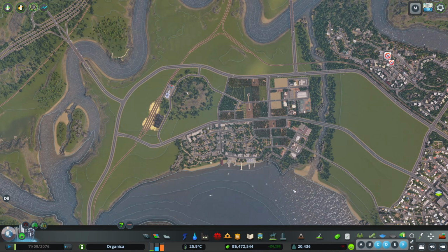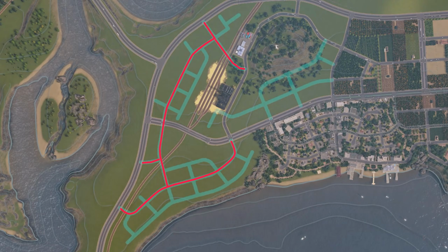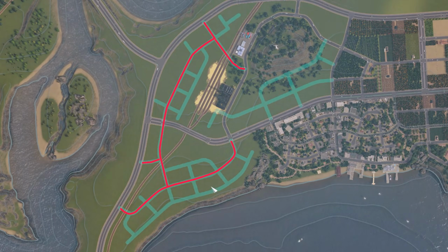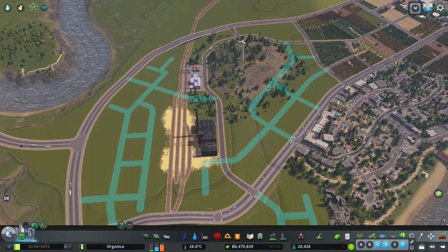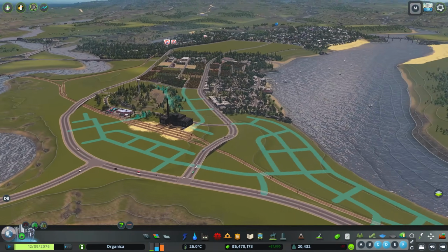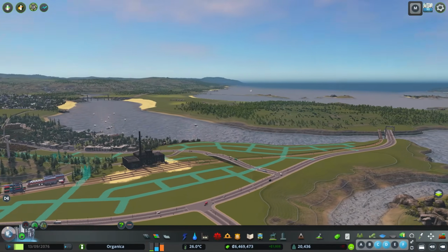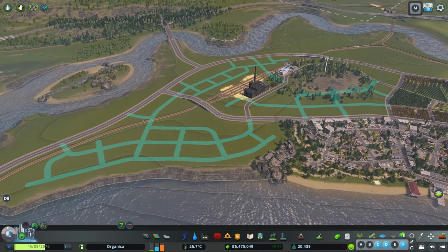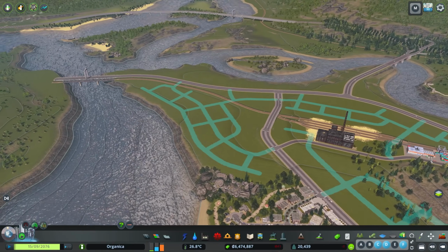The preliminary road layout I designed according to the master plan consists of secondary collector roads and local streets. I tried to create a road network that would form as few intersections as possible, with the main arterial and the boulevard. In this map, the land is quite fragmented due to the rivers. There are no large flat areas in terms of topography. To make efficient use of the land in this confined space, we are moving forward with a compact city layout.